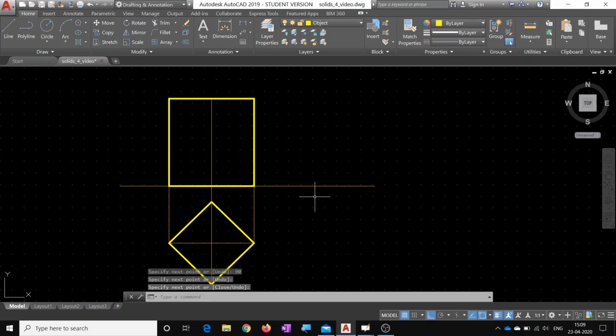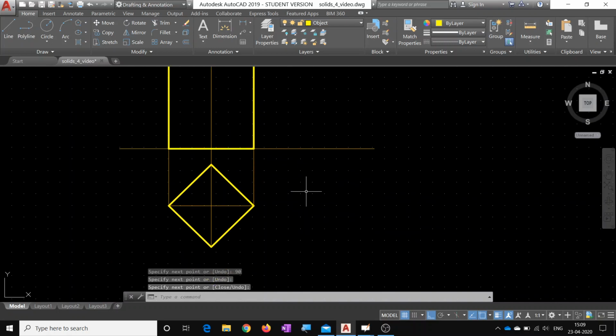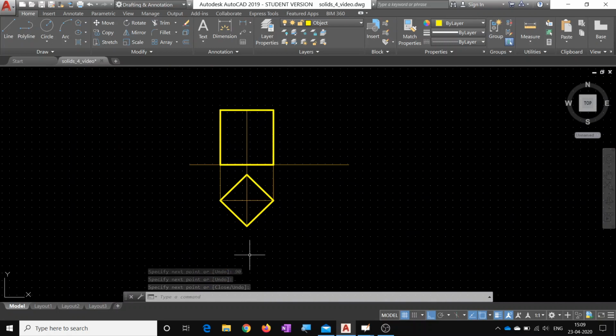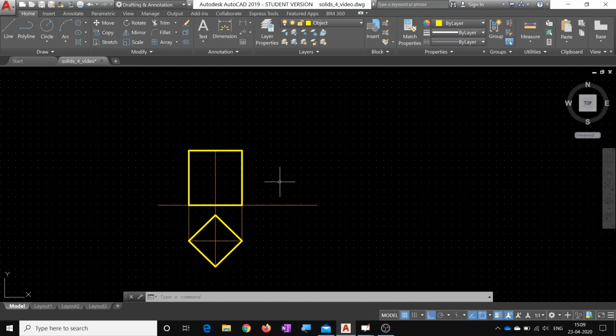All right. Now when you are seeing it for drawing the front view, you are seeing from this direction, what you will see is this edge also vertical, which is there. So that will also be visible. So let us show that also with object line. All right. So this is how we have completed the front view and the top view.